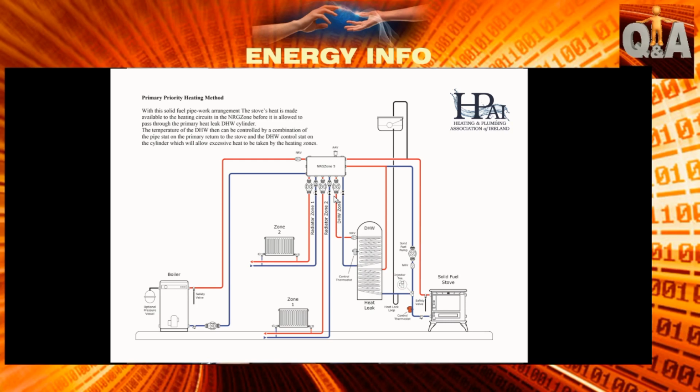Just to clarify that, what does the pipe stat on the return actually fire? It turns on the pump, the boiler pump down at the end next to the stove. Okay, that pump here, the pump above the injector tee there? Yes. And what does the cylinder stat do then? Well, if the other oil boiler was on as well, and you want to control your domestic water temperature, you need a stat on the cylinder anyway.